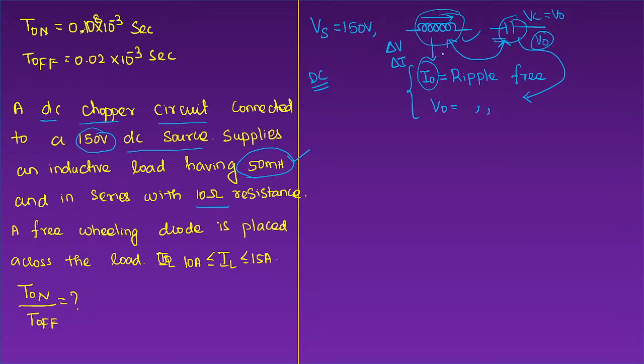I can't say we can use the same formula for all types of chopper circuit. But the capacitor is permanently connected across the output in all types of chopper circuits. So if the capacitor voltage is given, you can treat it as the output voltage. But this will not be true for the inductor. In case of the inductor, you should check what type of chopper circuit is given.